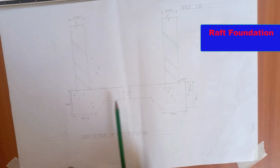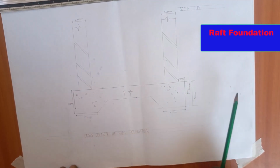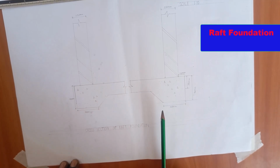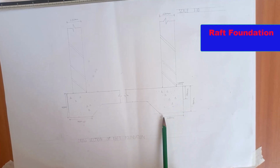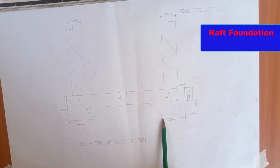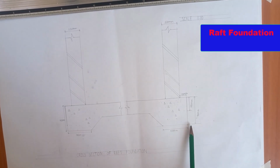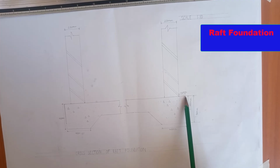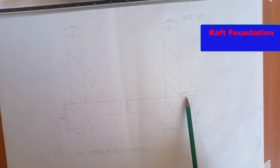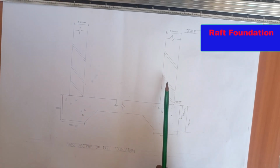So this is a raft foundation. A raft foundation is the type of foundation that covers the whole surface of where the building is. But you find that where the wall is, it is a bit expanded. So for this case, the distance from here to here is 400. Then the depth here is also 400. Then the offset from the external part of the foundation to where the wall starts is 100. And this is our external wall.